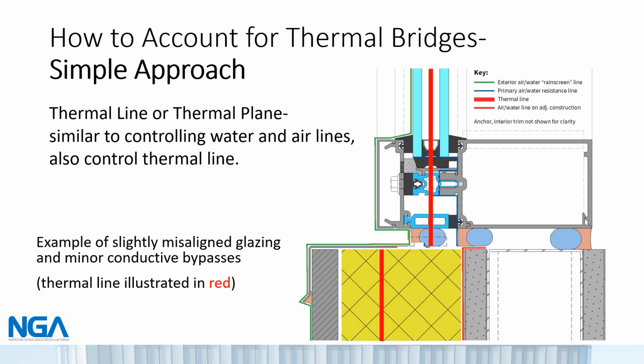While everyone, from architect to glazing subcontractor, recognizes the information conveyed in typical vertical and horizontal section cuts through the glazing systems, it's critical the perimeter details indicate the proximity and relationship of the glazing system to the air and water barrier locations in or on the adjacent construction, and how any anchorage details, sealant joints, and other components may interact or impact the glazing system.